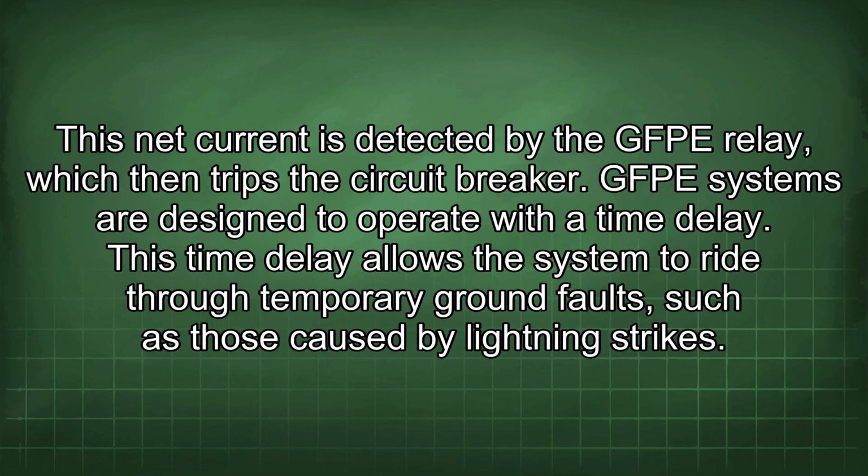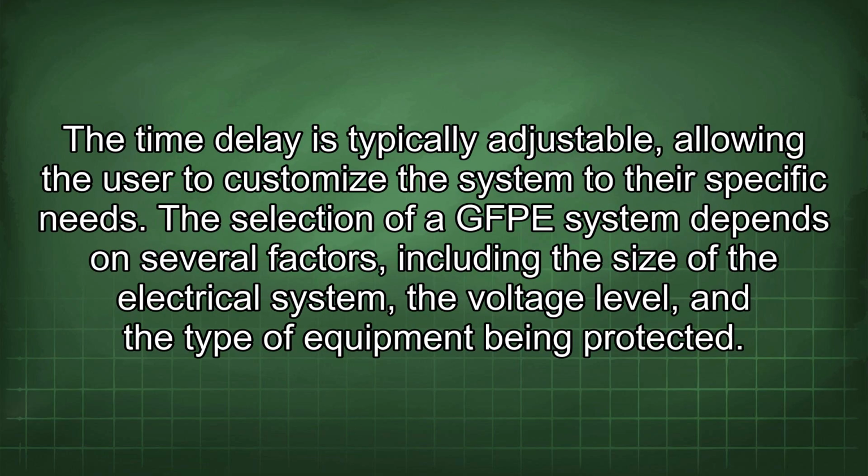GFPE systems are designed to operate with a time delay. This time delay allows the system to ride through temporary ground faults, such as those caused by lightning strikes. The time delay is typically adjustable, allowing the user to customize the system to their specific needs.